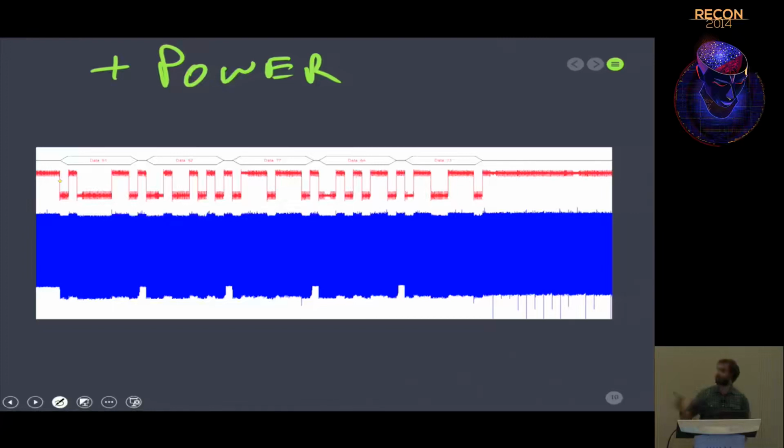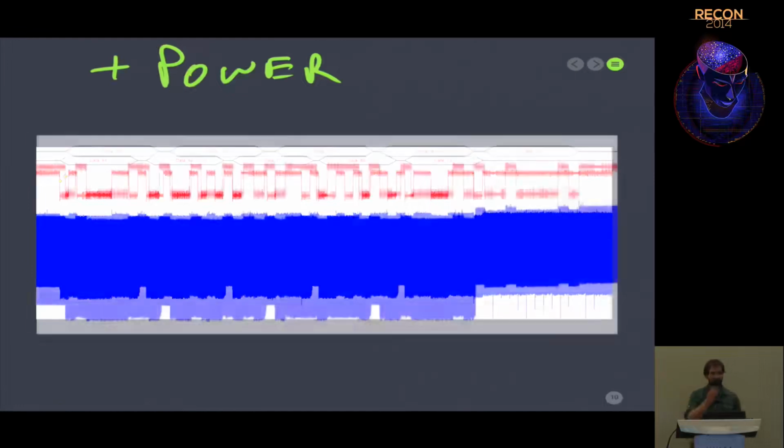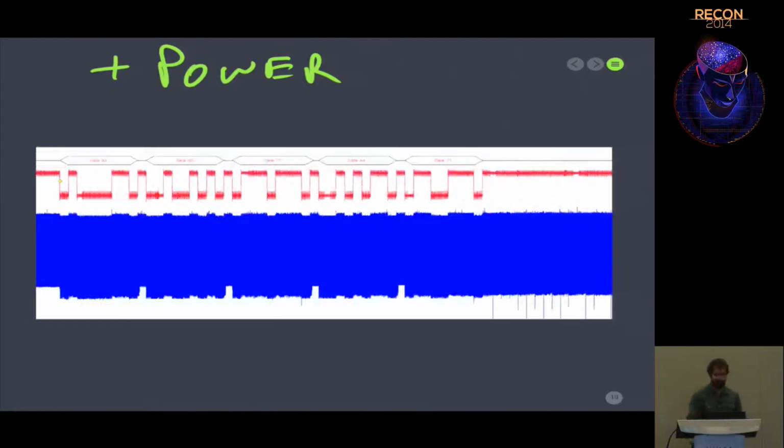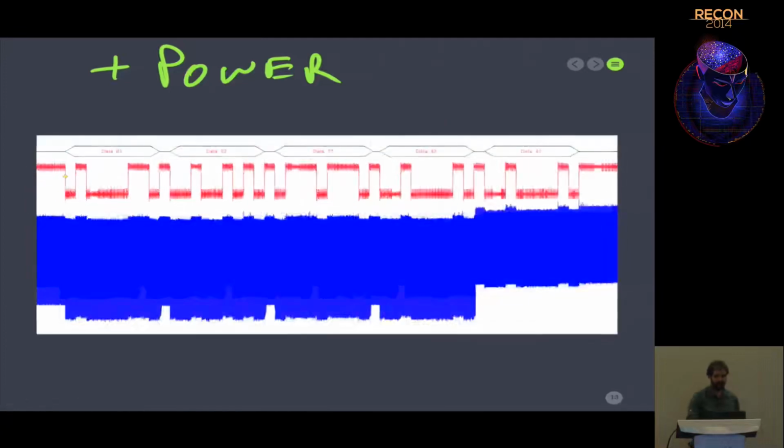And this is measuring the power as I put in the correct password, and then it goes off and does something else. Now, if I put in the wrong password, you see something very different. So what's happened here is, I guess you can see, this byte, I think, is wrong. And as soon as it's received it, so at this point in time here, it's finished receiving that byte, and it says, oh, spin into an infinite loop. So you can see immediately where your password is wrong.